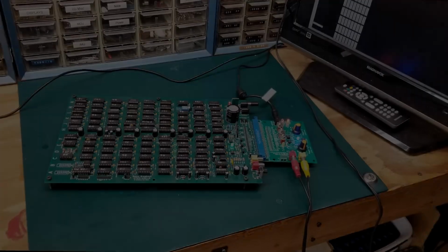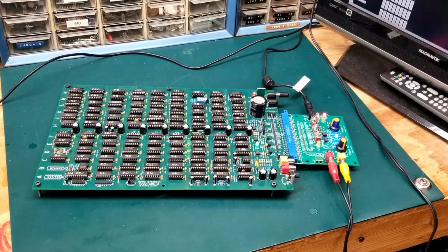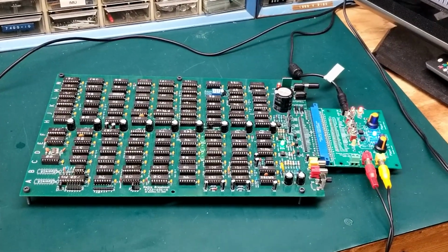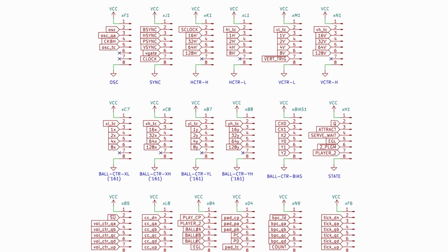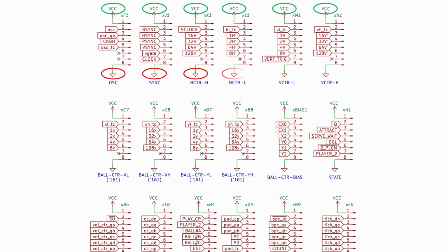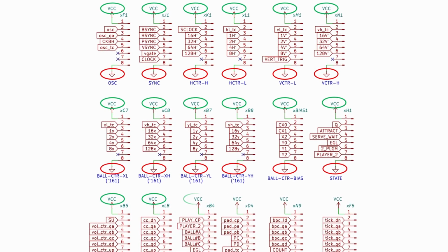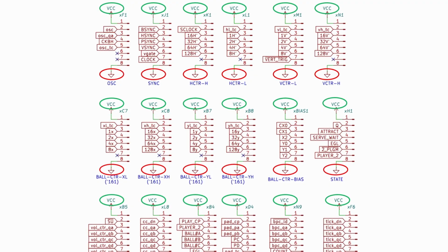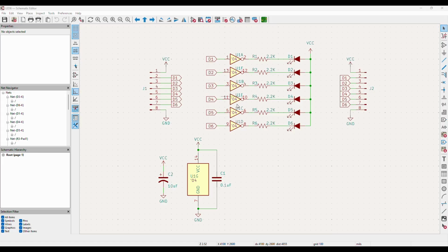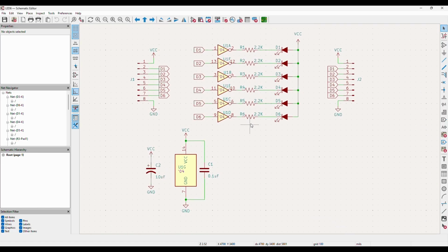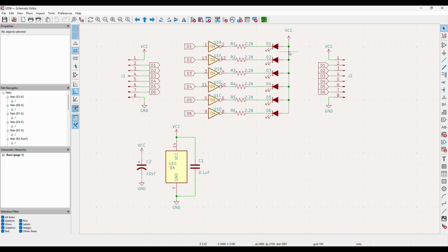In this video, I'll show you 3 breadboard widgets that also work on our retro headers. We were specifically consistent with our 8-pin headers by using pin 1 for VCC and pin 8 for ground. These particular widgets respect that convention. The first one is this simple display board. It uses a 7404 hex inverter to drive 6 LEDs per the 6 input signals.